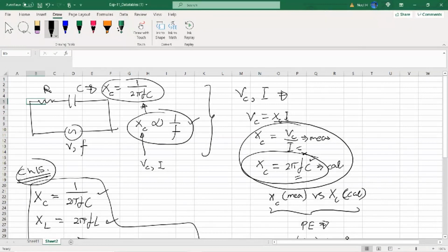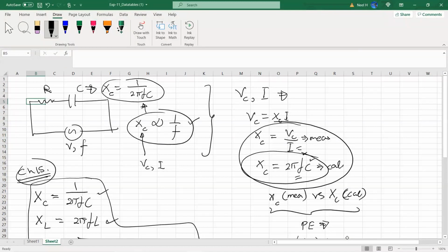So the measurements I need, we can do this experiment even without an oscilloscope. We don't really need the oscilloscope, because I just need to measure the voltage here, using either a voltmeter or the oscilloscope probe, or I need to measure the current passing through the circuit here. Those can be measured without the oscilloscope, but we'll use the oscilloscope because in the last part of the experiment, that also can be done without it, but if we have an oscilloscope, we can actually see the whole wave function. That gives us a really good idea about what's really going on in this kind of circuit, okay?